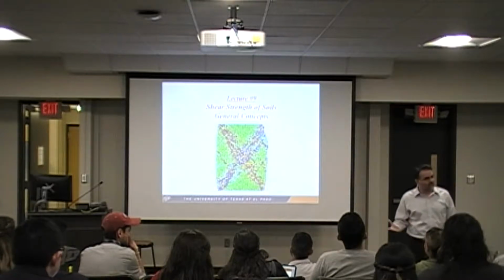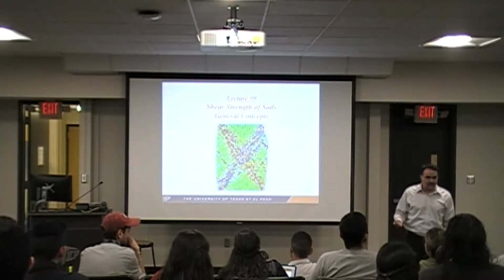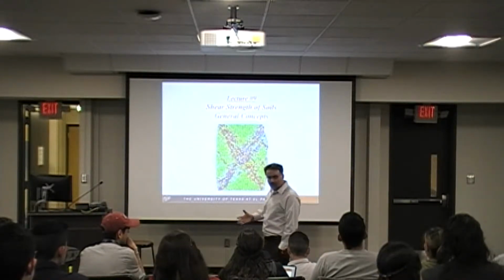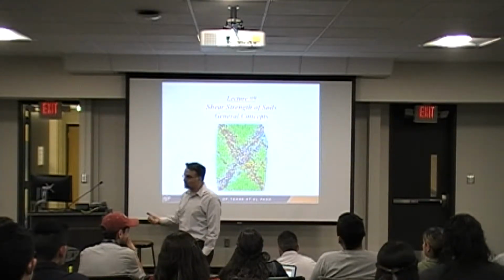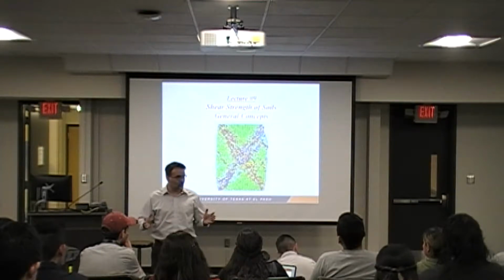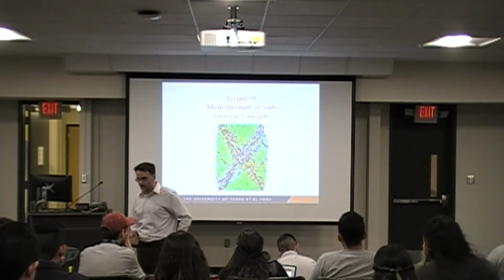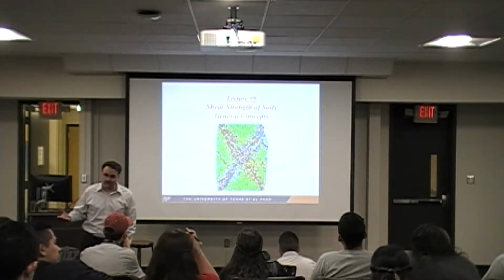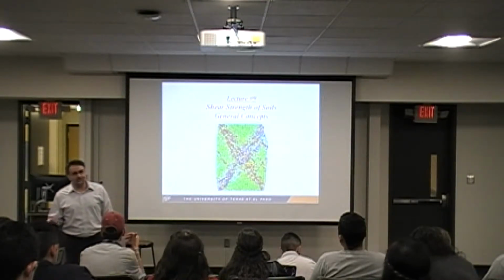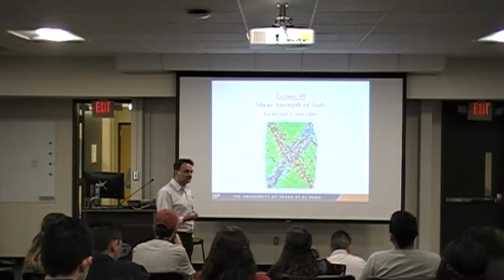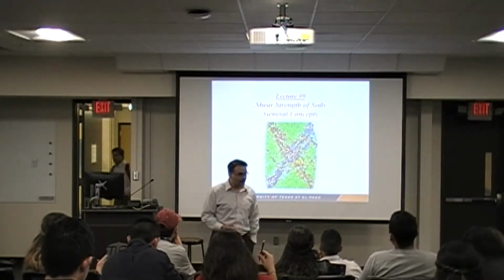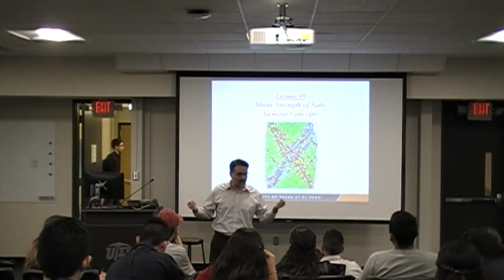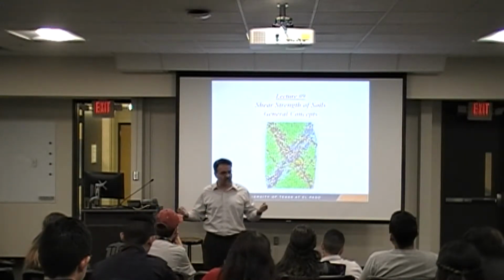When you want to design a structure, you calculate the stresses. Up until this point, in all your courses, you learned how to calculate the stresses. You develop your shear diagrams, bending moment diagrams, right? And what is the other thing that you need to know? You also need to know an indication of the strength of the material, right? Because you calculate your stresses and you want to compare that with something, and that would be the strength of the material.